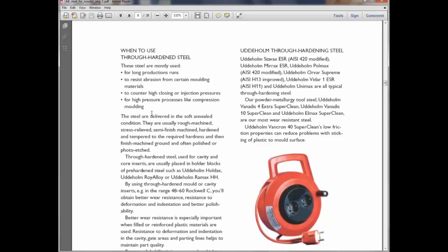Your mold material should be strong enough to hold that pressure continuously, because you are also pouring very hot material, like aluminum at around 800 to 900 degrees centigrade, inside the mold, so the mold temperature is also increasing. At that time the increasing temperature should not affect the strength of the mold itself, otherwise the mold can open, the mold can twist, anything can happen.